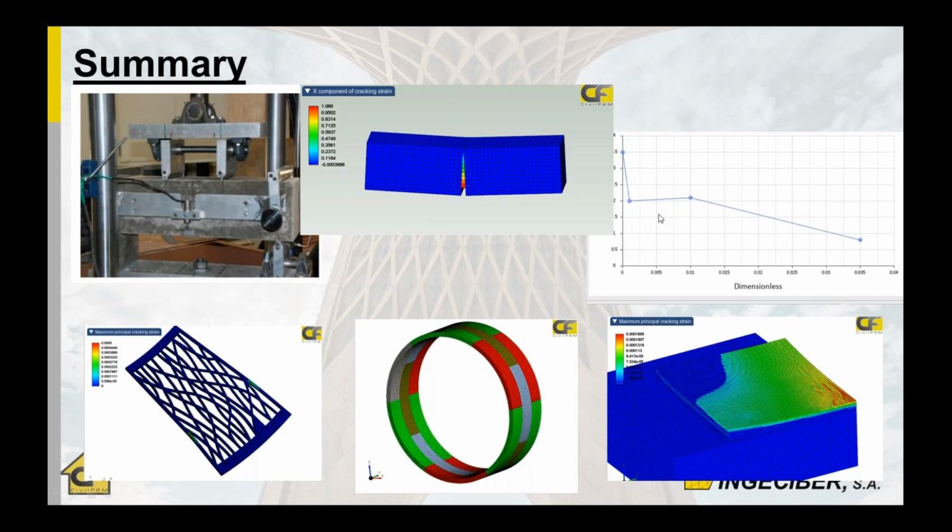In my case, for the tunnel lining segment, I used a bottom envelope of this test to be conservative. So the curve for the stress-strain relationship of my model, obtained from the force versus deflection of the beam, was the envelope of the minimum values of the test.